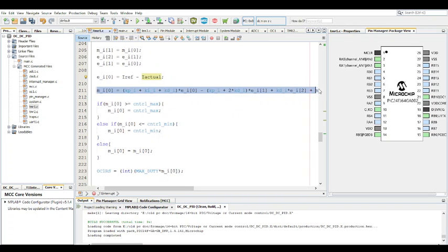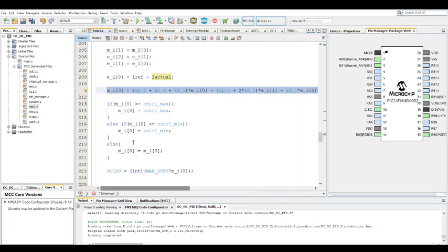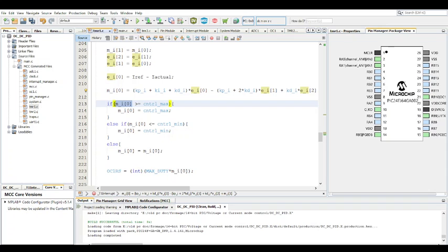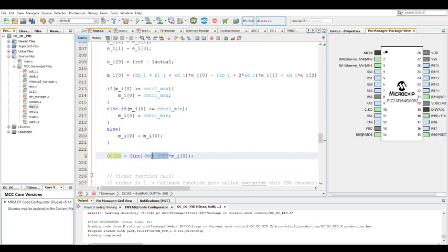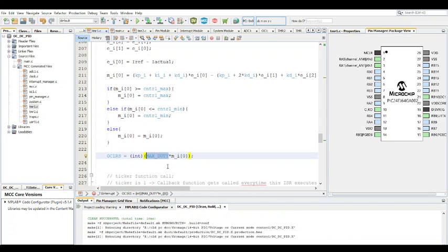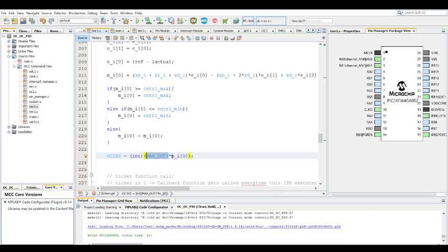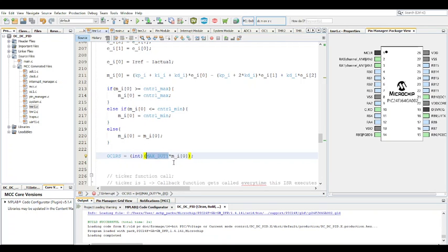and the same process. Only this time, obviously, we have different coefficients for the I, the error array is different as well, and the PWM input is different as well. The control max, the maximum DT and minimum DT are all the same. This stays the same because it's one PWM, and the max duty stays the same. It's so important to do it this way, so that you can move from controller to controller quite easily without changing the coefficients too much.